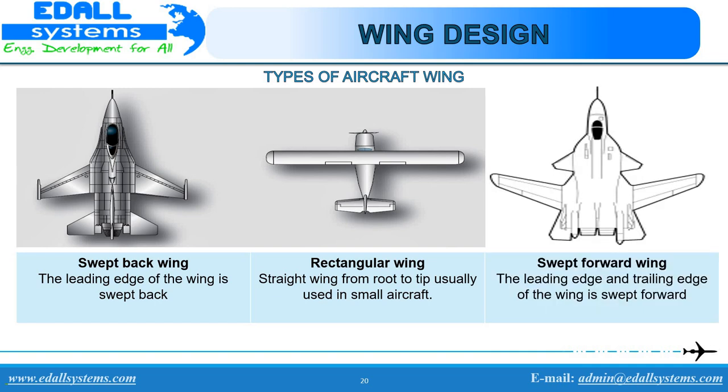Swept forward wing: the wing angles forward from the root. Benefits are similar to backward sweep. Also, it avoids the tip stall problems and has reduced tip losses, allowing a smaller wing, but requires even greater stiffness.